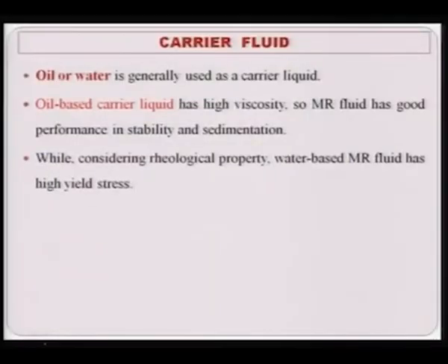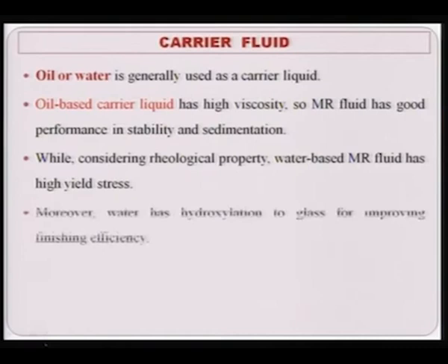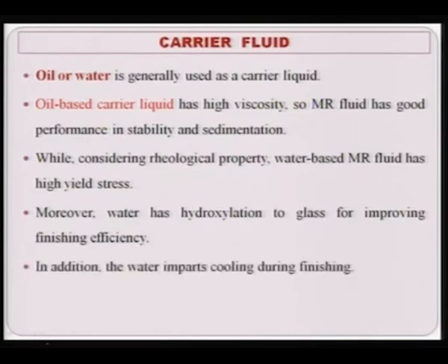While considering rheological property, water based MR fluid has high yield stress compared to oil based liquid. Moreover, water has hydroxylation to glass for improving finishing efficiency. In addition, the water imparts cooling during finishing. Definitely the cooling rate in case of water is higher as compared to the cooling rate in case of oil.